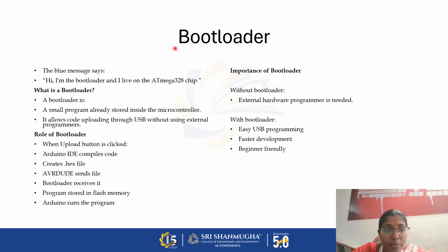The next one is the bootloader. In the previous slide, you can see the message, "Hi, I am a bootloader and I live on the ATmega328 chip." So this bootloader is available on the ATmega328 chip. What is a bootloader? A bootloader is a small program already stored inside your microcontroller. It allows code uploading through USB without using any external programmer. Without a bootloader, you would have to externally add a program to run it.